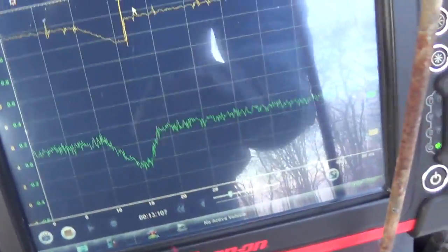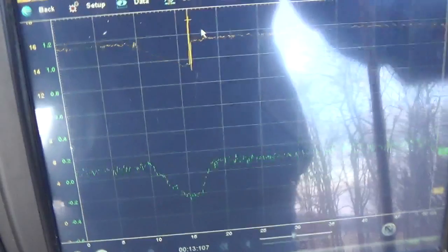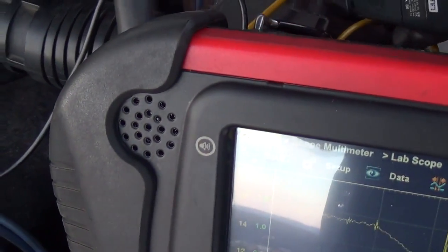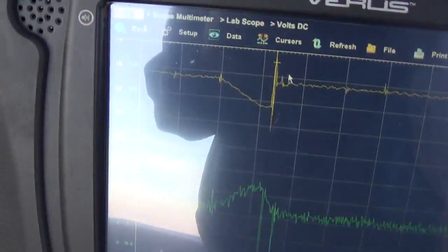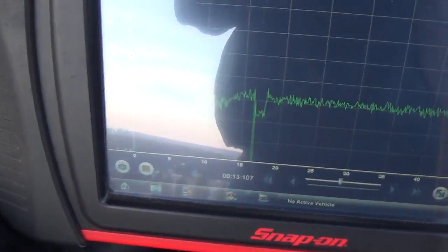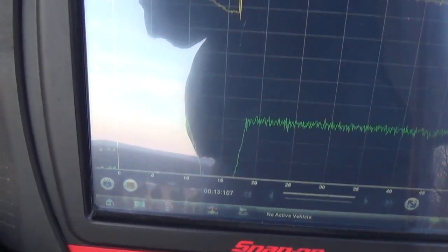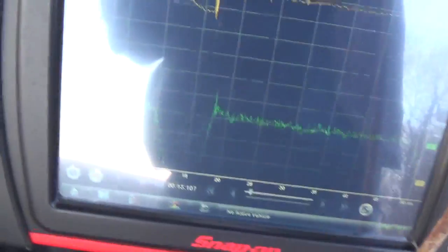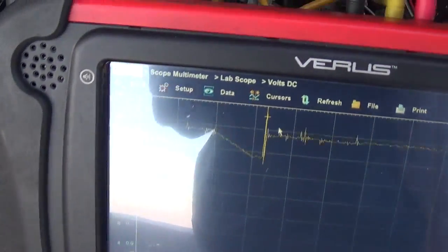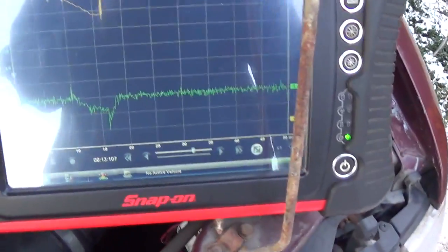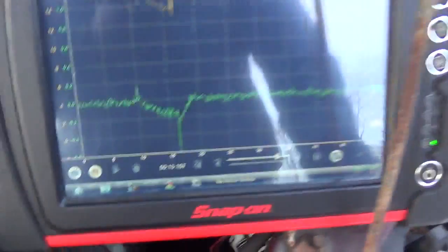So now we can safely say that that is kind of a ghost amperage. It's not real amperage going through our wire. It's actually just a clamp picking up magnetic interference. Now we can even experiment with this. I mean, see, there's no wire. I'm bringing it close to the coil. And look what we get. Wow. So in this case, we have to ignore that hump.